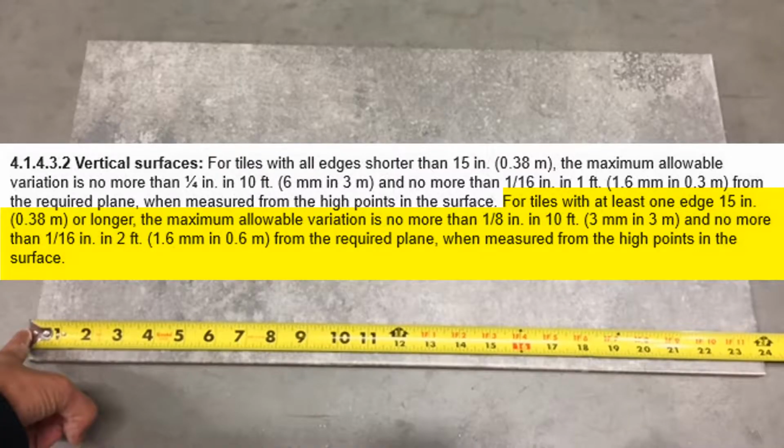For tile with at least one edge 15 inches or longer, the maximum allowable variation is not more than an 1/8 inch in 10 feet and no more than a 1/16 inch in 2 feet from the required plane when measured from the high points in the surface.